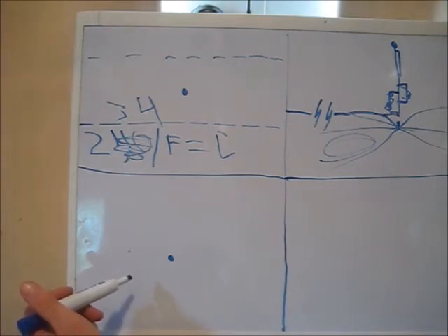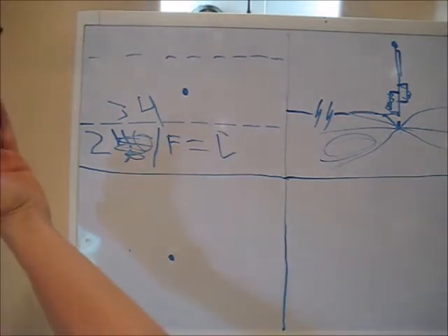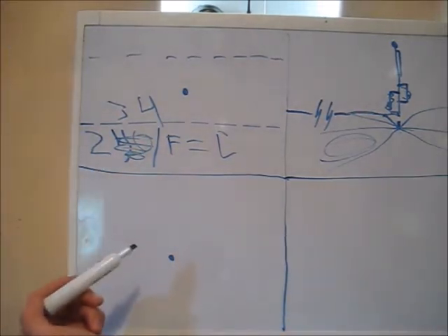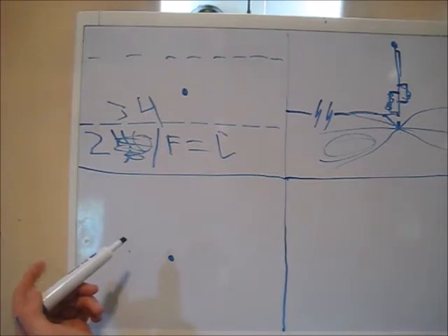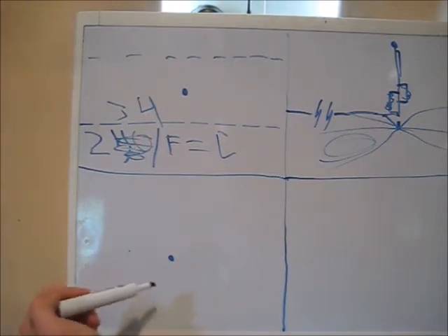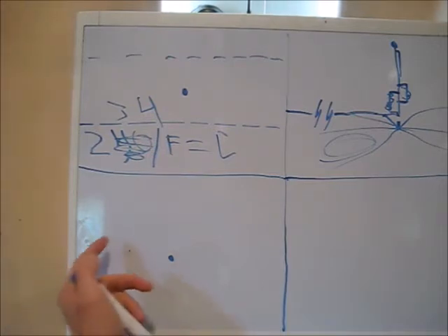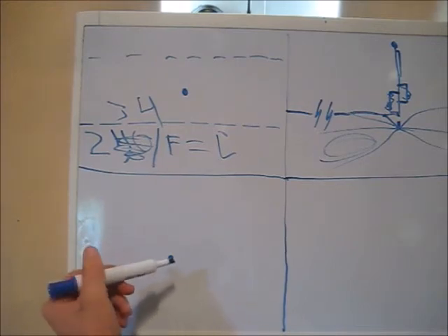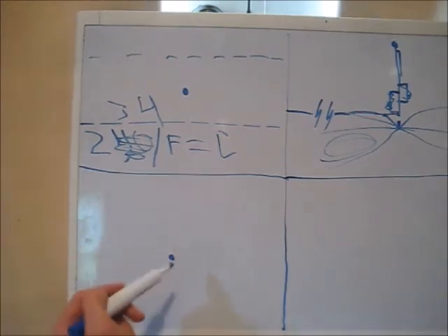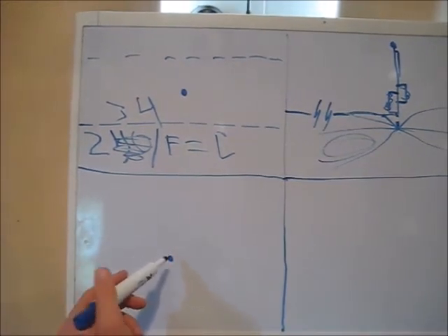Also, that signal has nowhere to go except into the ground. Big note, the ground is not an antenna. It's not technically conductive. The moisture in the ground and the metal contents are conductive, but the ground is not an antenna. So what radials are going to do is turn the ground into an antenna. You're giving that signal somewhere to go besides the dirt.